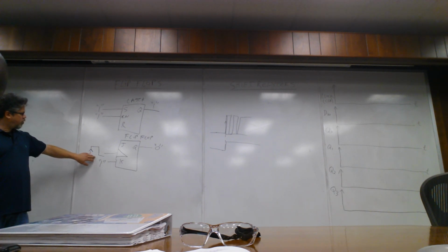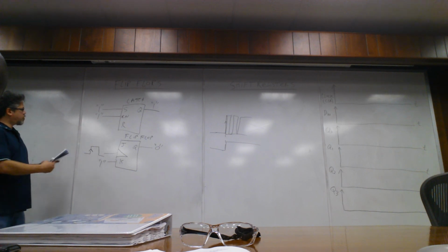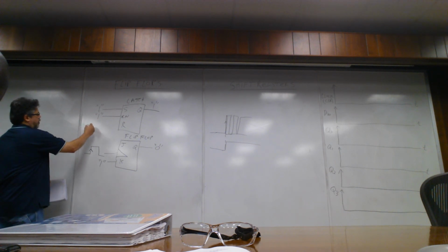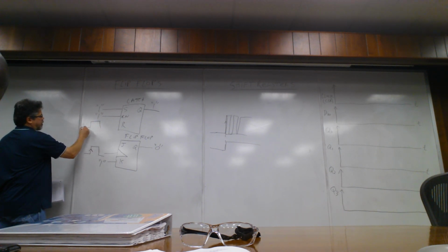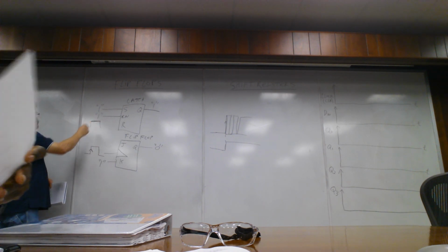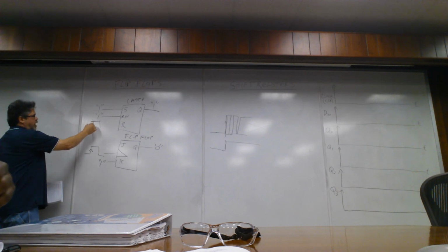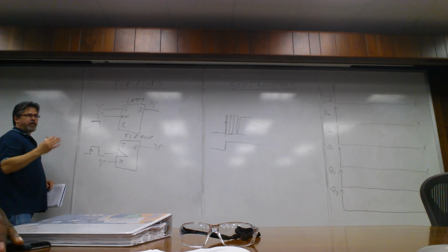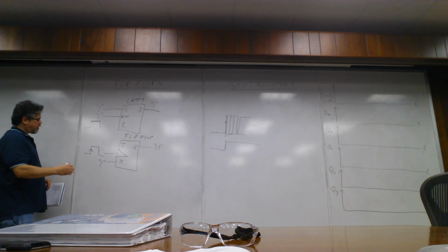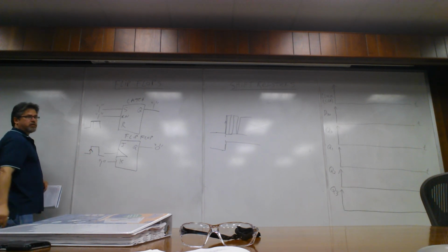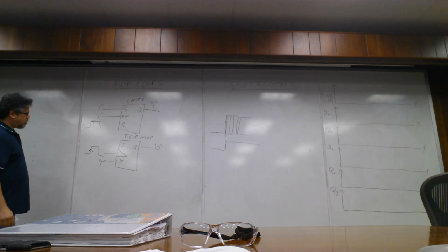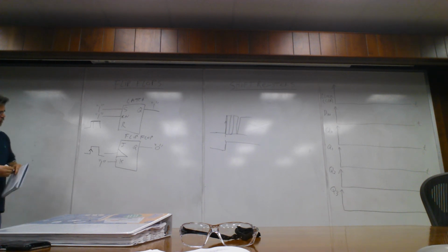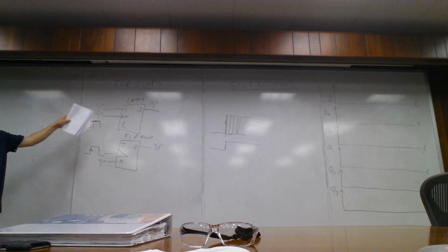But one is edge triggered. This is called level enabled, where we don't care about the clock. It's just this period. Anytime the clock is high, it's sensitive to what's on S. If S decides to drop, it's going to reflect, and we don't want that. If you're looking at something that happens very quickly, you want an edge triggered device like that. Okay, now continue with the flip-flop. Yeah, that's the flip-flop. That's the primary difference between the two.